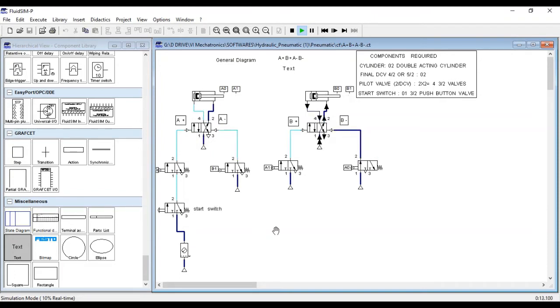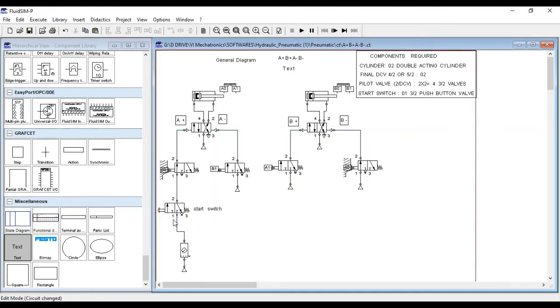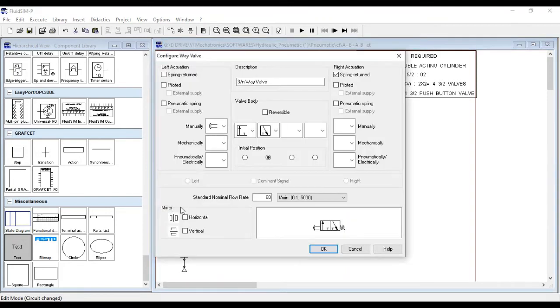What if I want a multi-cycle operation? The simple way to achieve multi-cycle is using this detent switch, a push button and detent switch. Detent switch means it will remain at that position unless it is pressed again. So you can take it as a toggle switch. Once you push, it will be on, and when you push it again, it will be off.